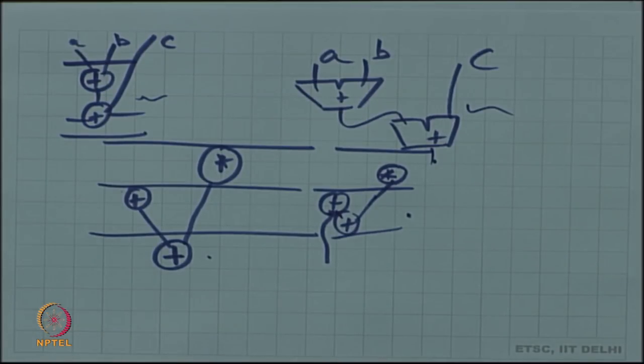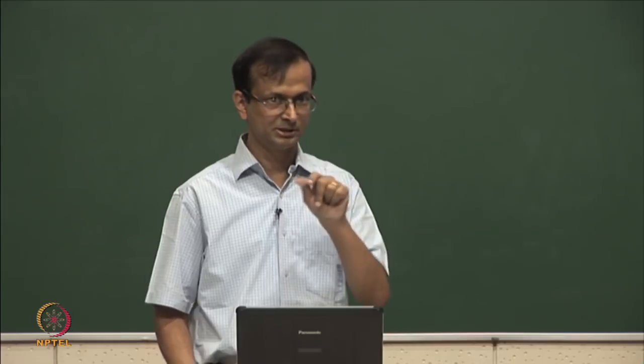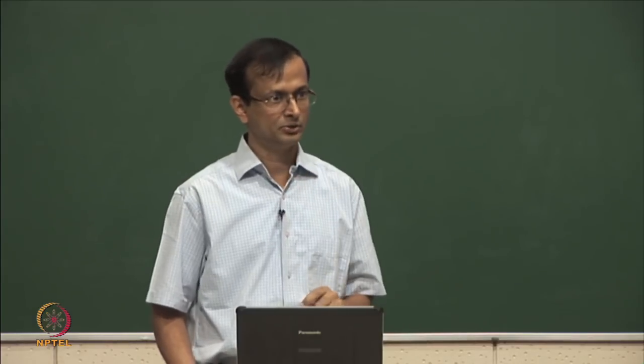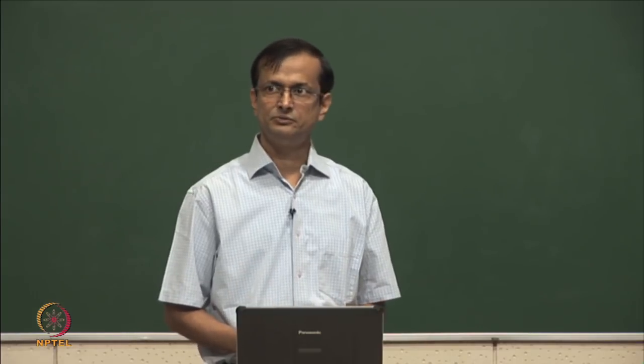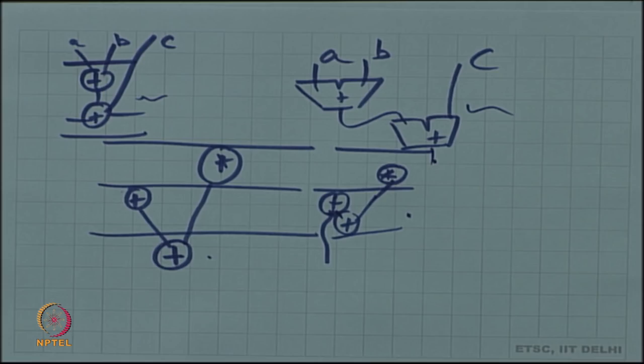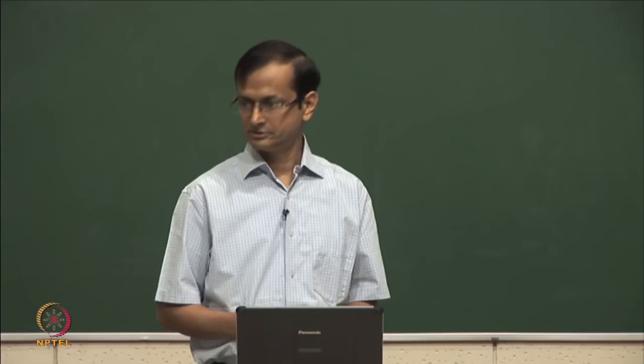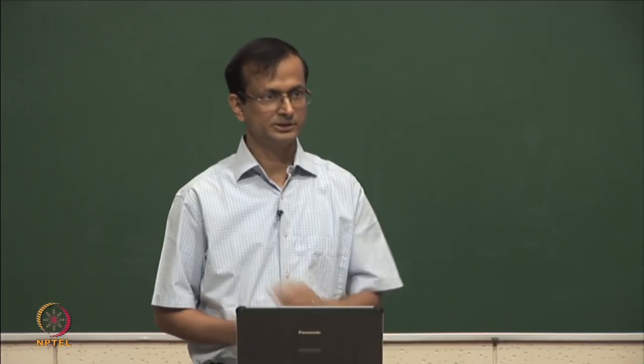We did do some merging in one of our transformations. Remember when we had that MAC operation, we actually substituted multiple nodes into one node. This isn't an example of that. This is a proper chaining in which you are instancing both the resources and are connecting them up in a way that both are being scheduled into the same clock cycle, but otherwise there is nothing complicated that is happening.